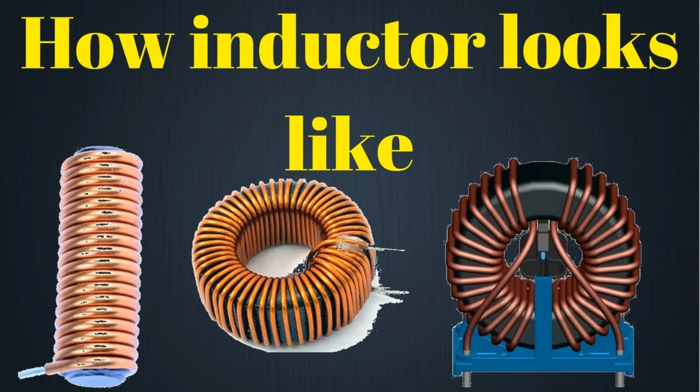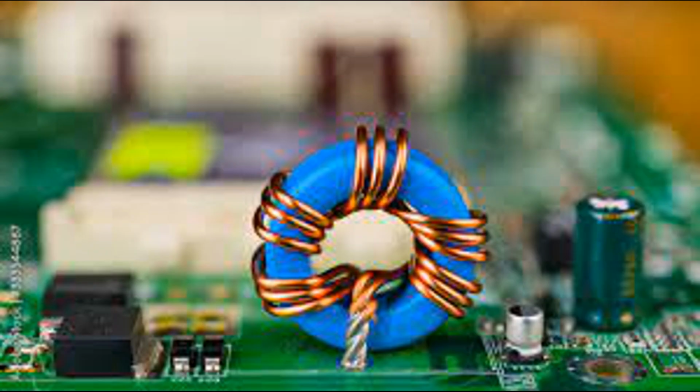Key points. Impedance. As frequency increases, the impedance of the inductor also increases, making it an effective choke for high-frequency AC signals. DC path. Inductors present very little resistance to DC, so they allow DC signals to pass through with minimal loss. Applications of choking with inductors.